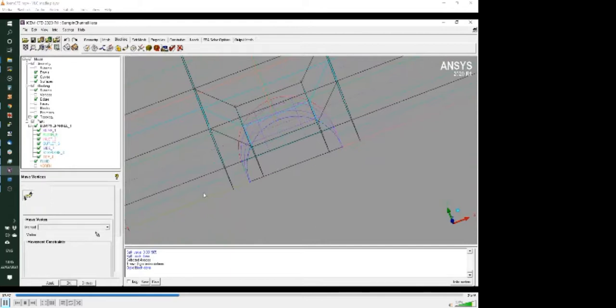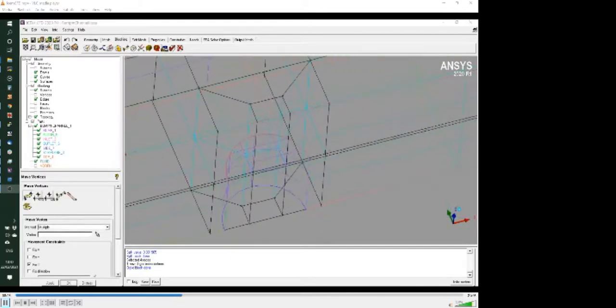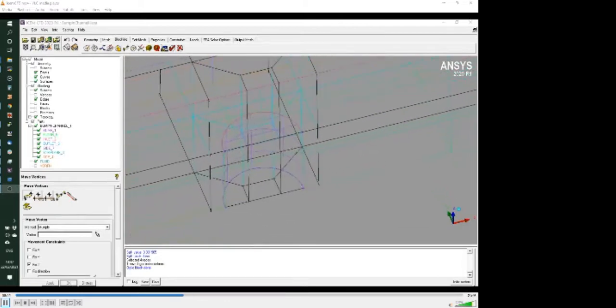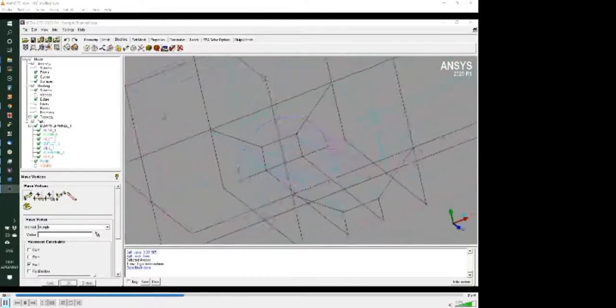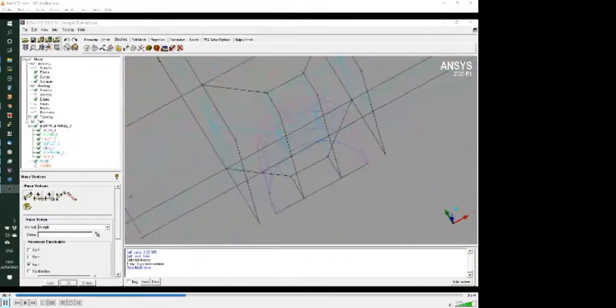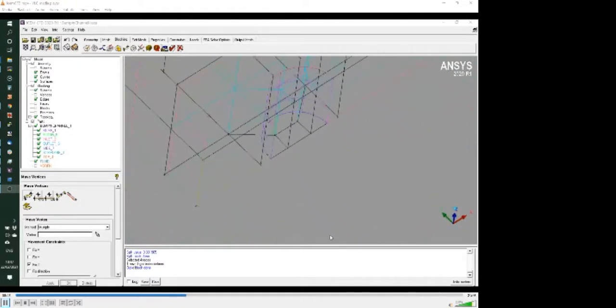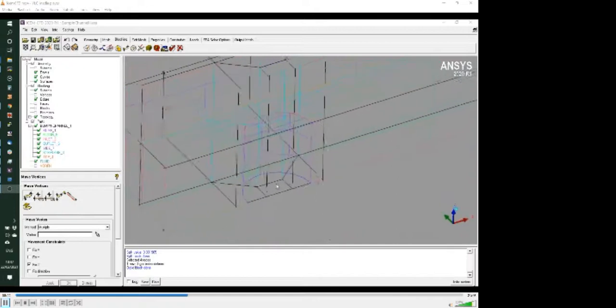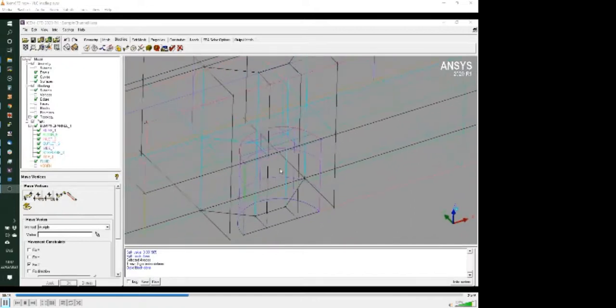I've cheated a little bit. I've made like a cook in a TV cooking program. So I've done the tedious bits while you weren't watching. So I've moved the vertices so that they're inside that cylindrical object. And then comes one of ICEM CFD's tricks, which is to remove the blocks that we're not going to need.